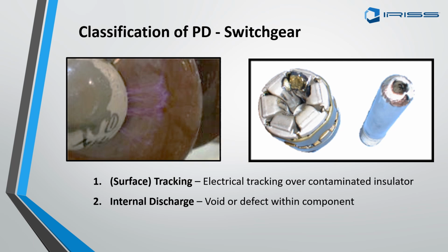And number two, it would have to travel through the insulating medium and then into the surrounding air. So it has to pass through multiple mediums to get to a place where we could listen to it with a handheld ultrasound device. So the level of sound energy that would transmit through those multiple mediums would be significantly diminished from the original fault. And the original faults tend to have very, very low levels of sound energy generated in the first place.